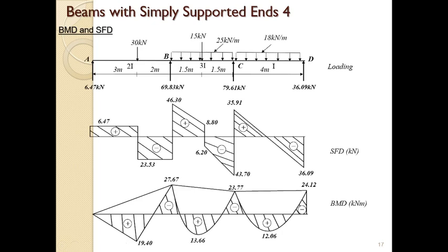You do it. So while these other ones are the same, where you have this moment here and this moment here, to know what is at the mid-span, it is this plus this divided by 2. You have something here, and this moment was originally WL squared over 8. So you now subtract this from WL squared over 8. That's what gives us what is here. The same thing is done here at this moment. But please take note that the load here is not just going to be WL squared over 8. It's going to be WL squared over 8 plus PL over 4.